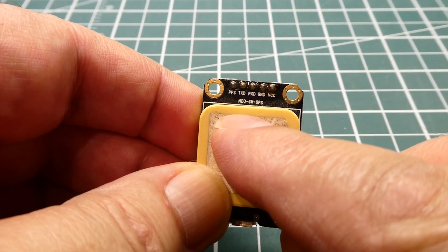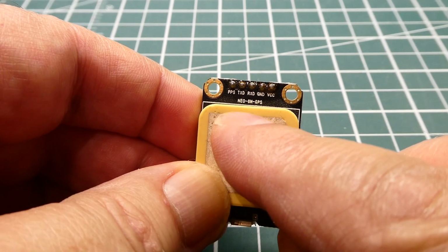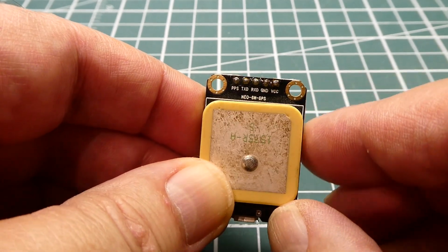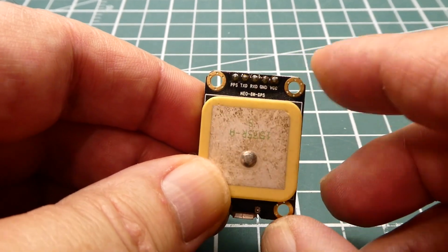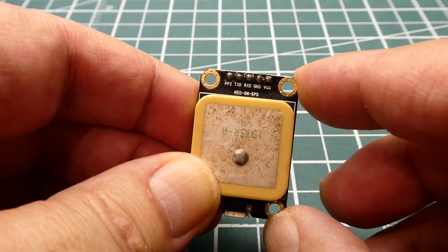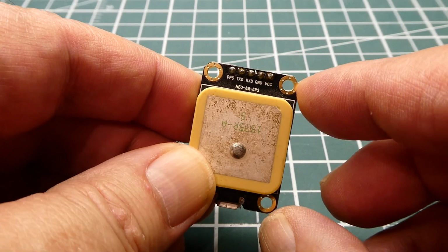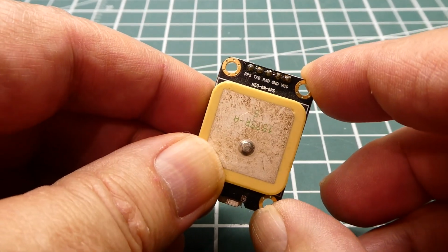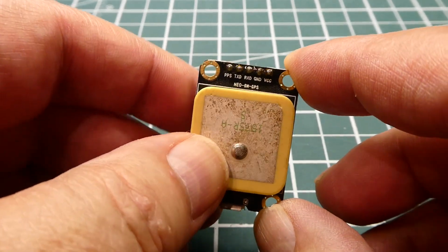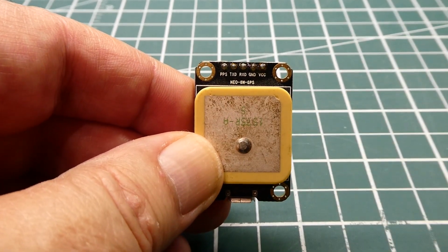Now the TX output is going to send out some ASCII strings, and they're NMEA 0183 protocol strings. And in these strings is going to be the data that we want to extract. So there's 2 sentences that we're going to use. It's the GPGGA and GPRMC. And with those 2 sentences, we could extract the data for our GPS projects. So we'll have a look at those 2 sentences and what kind of data there is in the data fields.